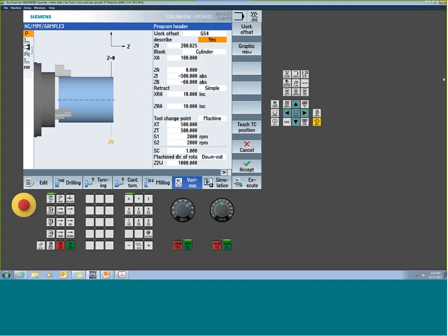You don't have to use the main. That was also why we had that transfer option of main to sub, or sub to main. You could start from either one. Can the two spindles work two different parts without making a transfer? Yeah, absolutely. Nobody says you couldn't be jumping between the two parts, but at that point you're using it as a glorified chucker machine, so you're going to stop after the program cycle. So the question was, he wants to work on two different parts on each of the spindles. Just jump between the two work coordinates, and then you can run any tool path you want there. But keep in mind that stack position. It's important that the offsets get set properly.